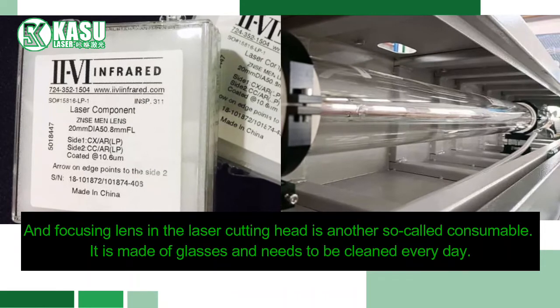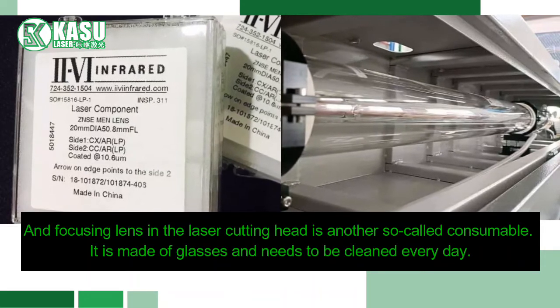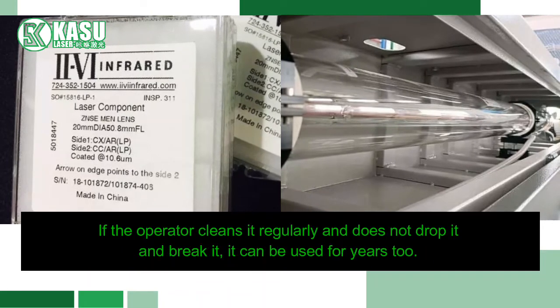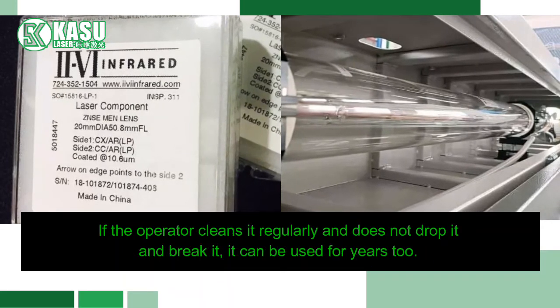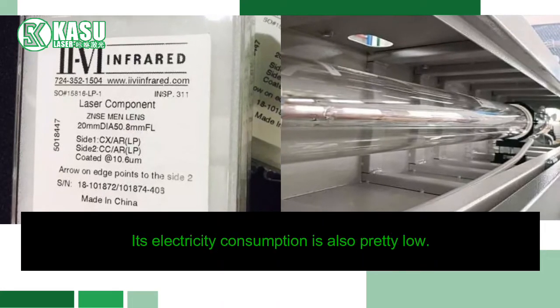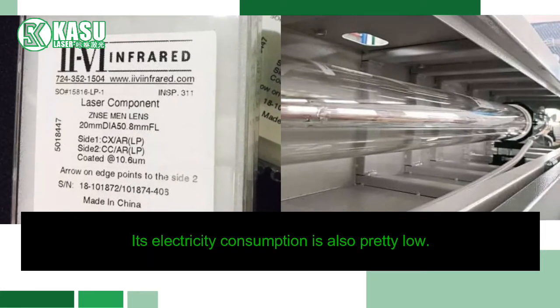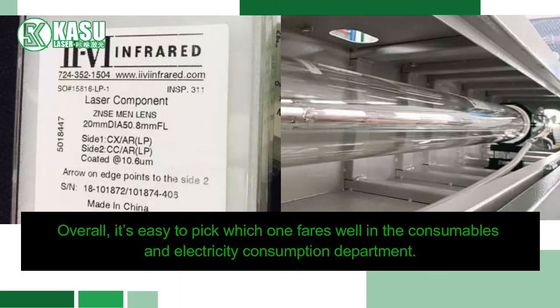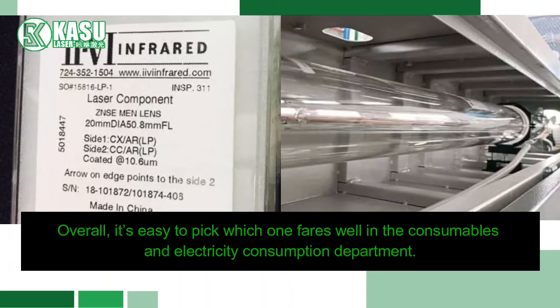And focusing lens in the laser cutting head is another so-called consumable. It is made of glass and needs to be cleaned every day. If the operator cleans it regularly and does not drop it and break it, it can be used for years too. Its electricity consumption is also pretty low. Overall, it's easy to pick which one fares well in the consumables and electricity consumption department.